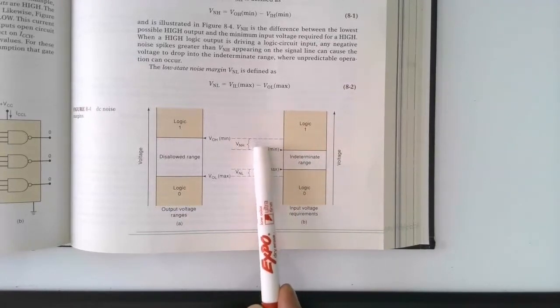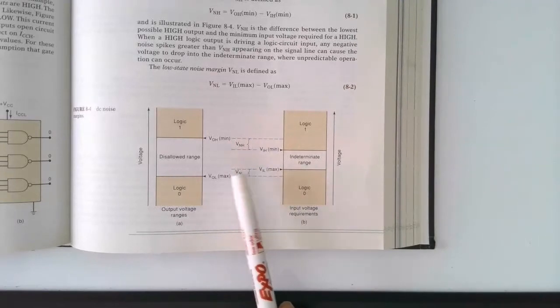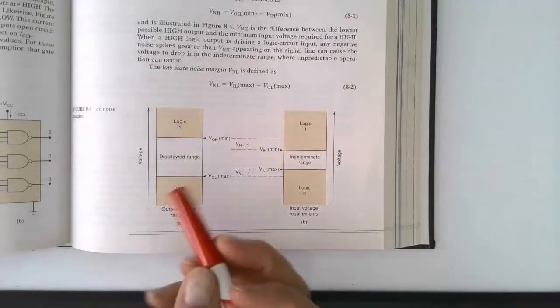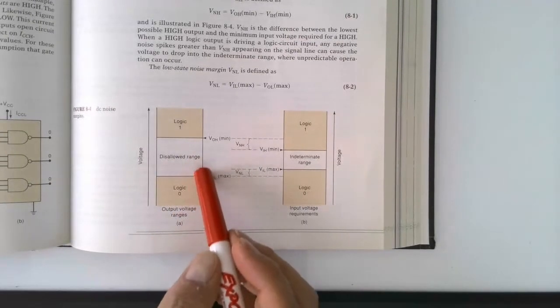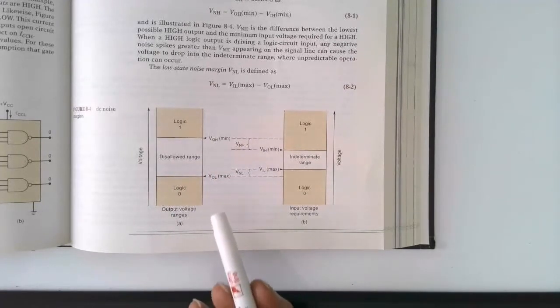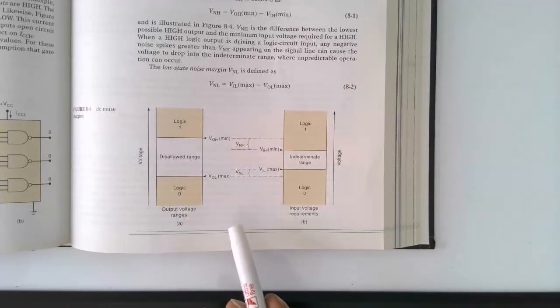And what we have between these two are what are called the noise margins. For example, if we had some noise, some signal that was actually like a little pulse riding up above here, it might cause a problem. And for TTL, the noise margin is pretty small. That is one of the problems or disadvantages with TTL, that if there's noise in the system, it's more susceptible to the noise. So already you can start to see some of the disadvantages with TTL.